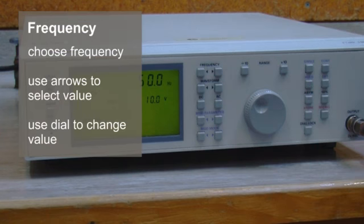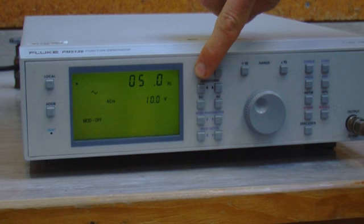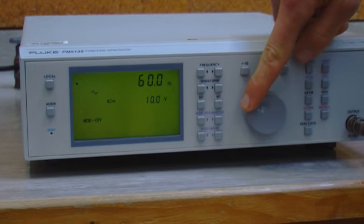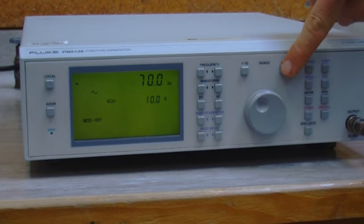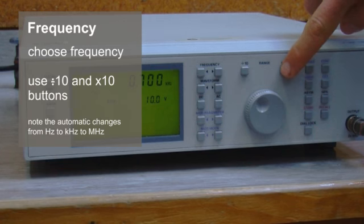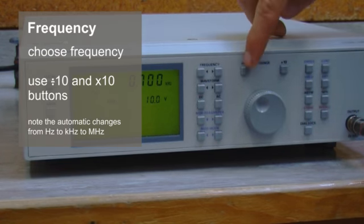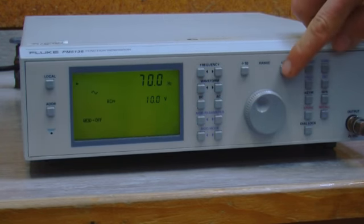So, set up, we can adjust our frequency. If we click the arrows at the top here, we can change whichever value we want to change by using our dial. You can multiply by 10. So this is changed now to show kilohertz on the screen. If we divide by 10, we've got back to hertz. And you can use this button many times to get higher and higher frequencies.